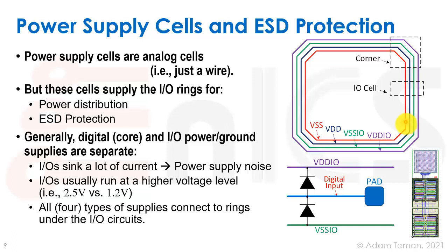So we're going to have at least 4 power supply IOs, and we're probably going to have at least 1 on each side of the chip, probably many on each side of the chip. When we go over to flip chip, it's not exactly the same thing. We do need these rings in order to provide the ESD protection even in the flip chip. But we can stick our IOs in the middle of the chip. We can make a little line of IOs.